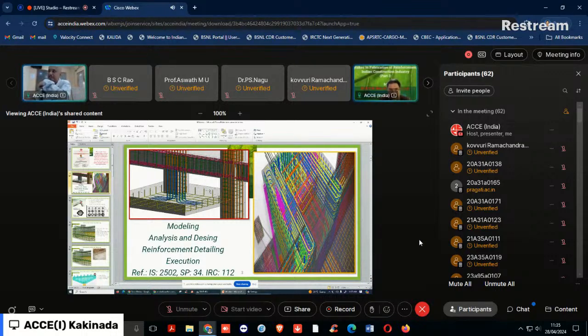Because there is a higher cover for the sides and a lower cover for the bottom, the permeability of liquids which are harmful to the concrete is very important. We have two types of permeability: permeability passing from the bottom of the concrete or footing, and permeability of liquids that can be water or harmful chemicals like saline water or oxygen intake, harmful sulfates or chlorides, ion migration, whatever harmful deteriorating materials ingress into the concrete body, from the bottom or from the sides.